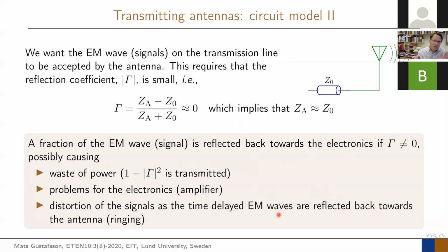So if you have cables which are not matched perfectly, so both of them are not matched, a signal will start bouncing there. And then you get an add-on on these with slightly time-delayed signals. And that's, of course, you don't want to have. So again, it's important to match the antennas. If we can do it, we should definitely do it.